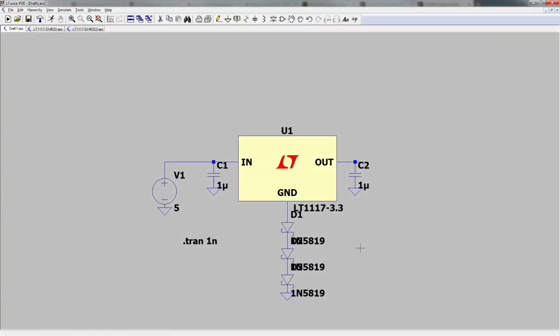So here is an example, and this is applicable to all fixed voltage regulators. So yeah, the goal is to raise the voltage here at the ground reference point, and one way is just by using some Schottky diodes here. Every one of these will raise the ground voltage by 0.2 volts. So by shorting some of these, you can get your original voltage plus 0.2, plus 0.4 and finally plus 0.6.